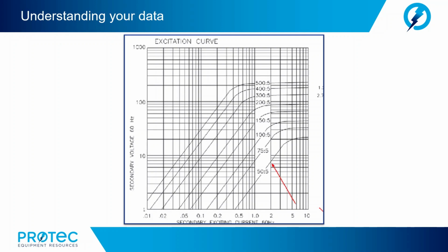Now, in this example, the CT that was tested was a Model 594 manufactured by Instrument Transformers, Inc. Note that the current at 2 amps is very similar to what the captured test results had shown. For this CT, however, the knee of the curve is up around 5 amps. Therefore, when the test was run, the test set stopped at 2 amps and not enough data was captured.